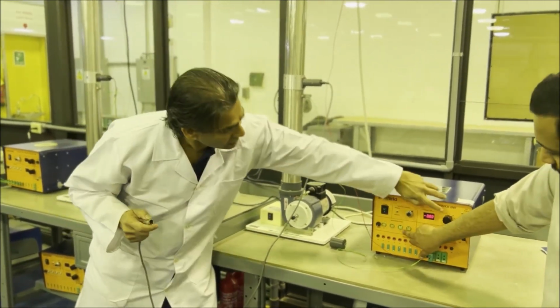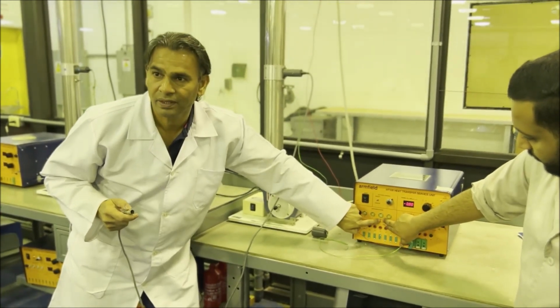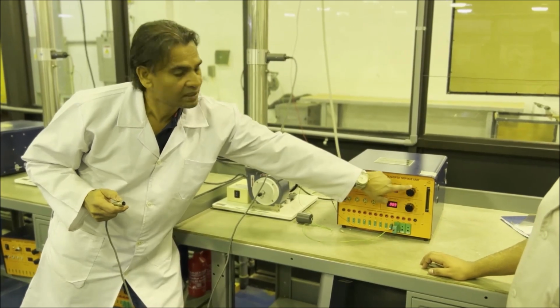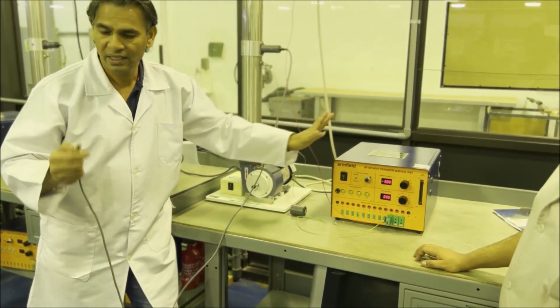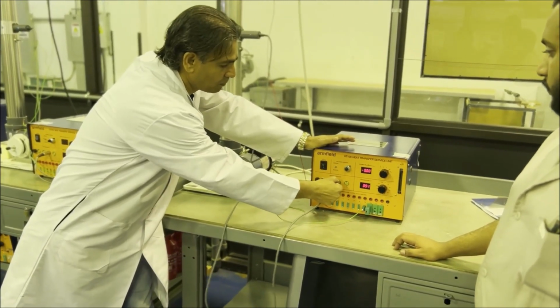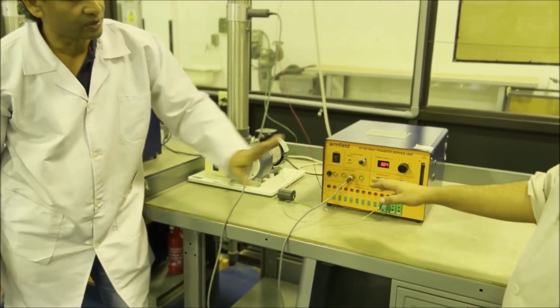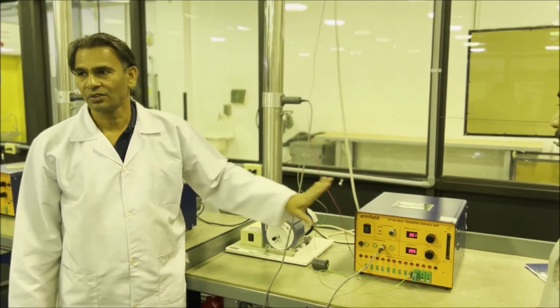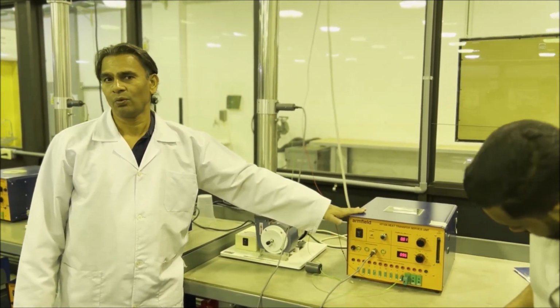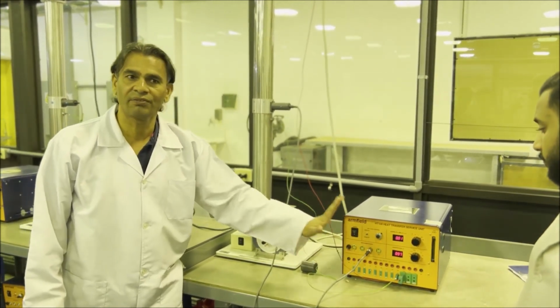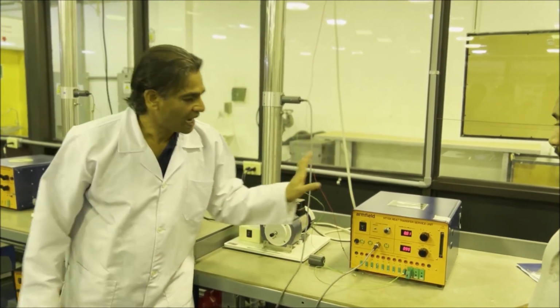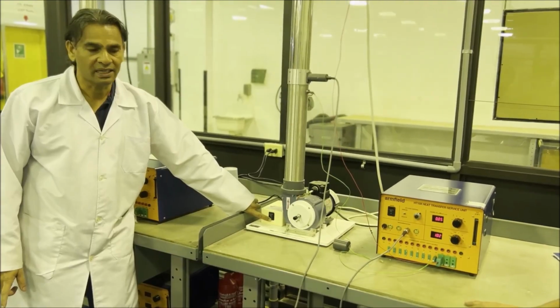So where do I have to connect? UA means velocity, so it will give you the velocity. If you connect here, no, wrong. It is always connected here, nobody will plug. The difference will be the reading, because this is for water and there is nothing here. Okay, so this is a service unit. Which service do you want? We want velocity of air, so I connected there. So this cable is connected to UA, keep this on UA, start the fan.